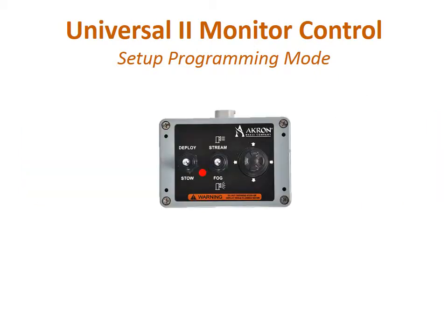After a few seconds, the system status LED will begin to blink slowly. This indicates that the setup mode has been entered successfully. If the control device does not have a status LED, an output for the system status is available from pin number 7 of the U2 Vehicle Interface Connector J1, which can be wired to a separate indicator.